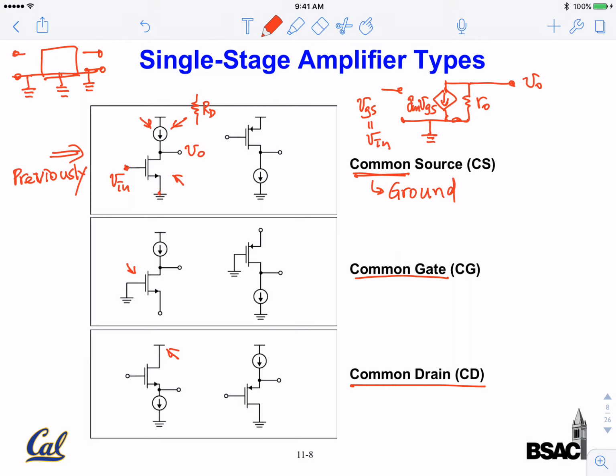So that would be this circuit, and it's so simple. We can finish all the analysis here. So the difference between RD and the ideal current source: an ideal DC current source, when we convert to the small signal equivalent circuit, is open. So that's easy. So this is the entire amplifier circuit. It's basically just the transistor itself. That's the whole amplifier circuit.